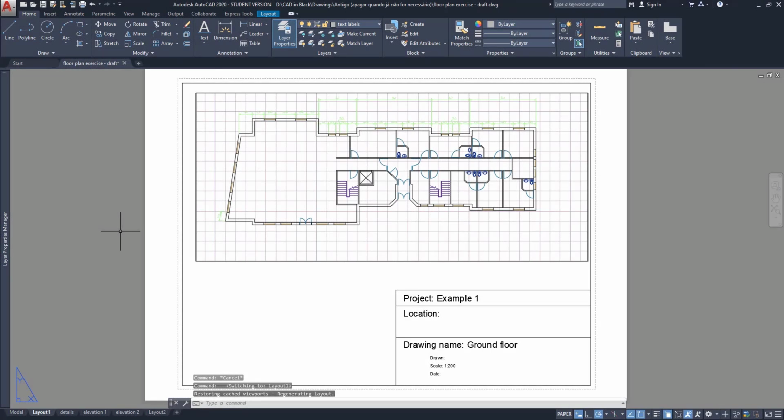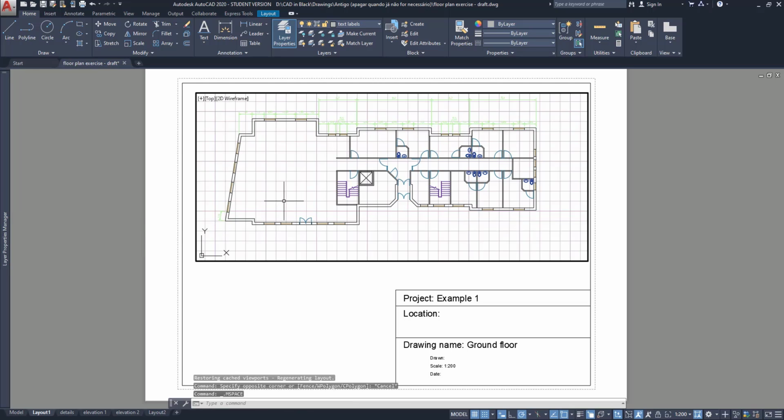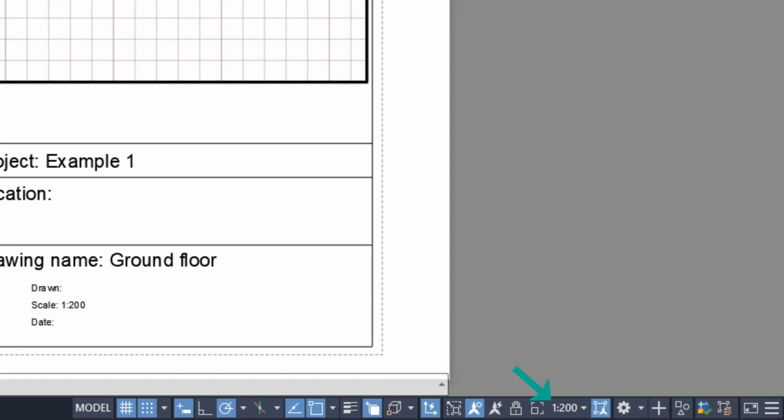Annotation in AutoCAD. In the next part, we will focus on how to insert annotative text and dimensions. It's simple, we just need to play a bit with scales in the workspace. The text height that we insert for our text is actually the real size that will be printed. For example, in Layout 1, I want to write text in this viewport with a text height of 0.005 meters. This is the procedure. First, check out the scale of the viewport. Double-click inside here and I can see it as 1/200.